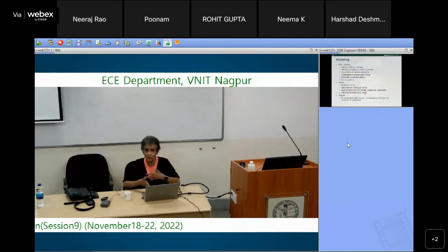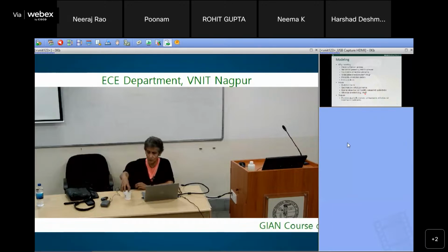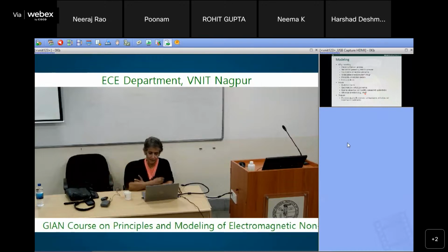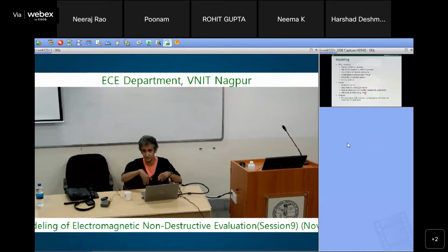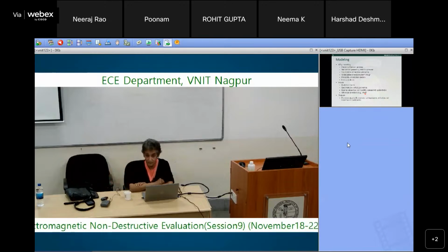We have developed another student thesis which was on the probability of detection model. So you have a coil, liftoff can vary, but sometimes it can also tilt. And when it tilts, what happens to the signal? So there's a variety of things, but it's nice to quantify all this using a probability of detection and say this is how the signal is going to change. So we use it extensively.